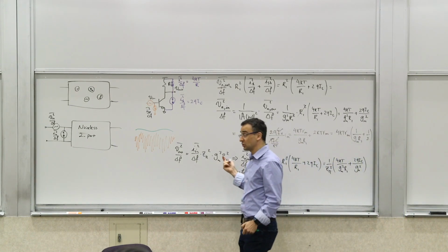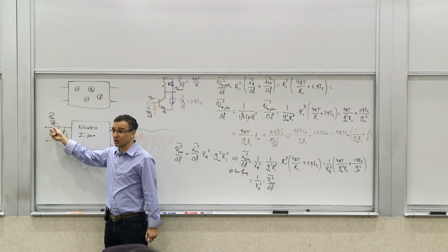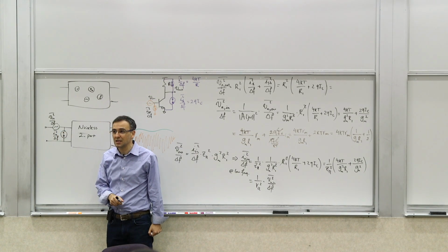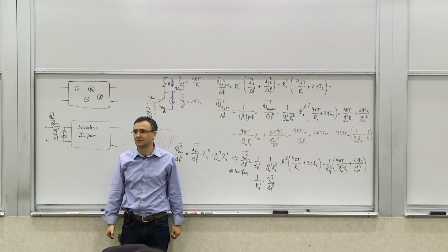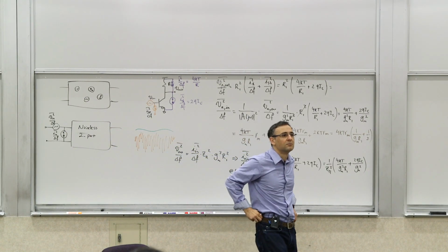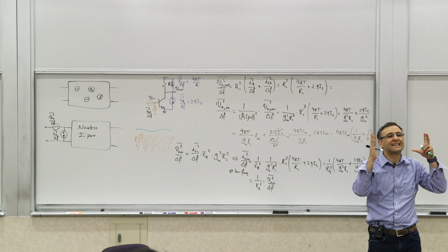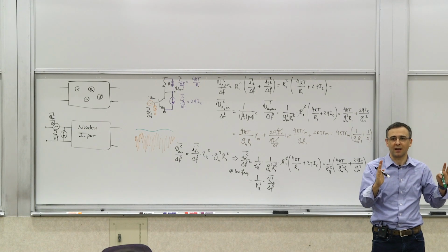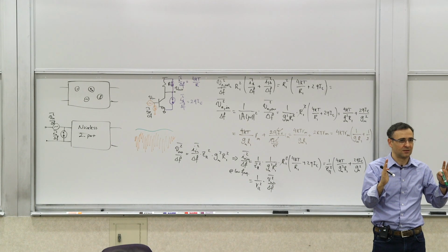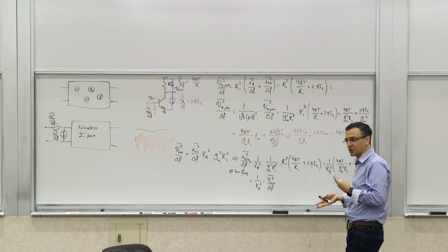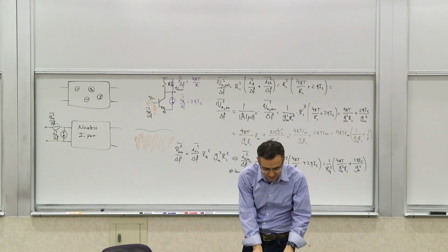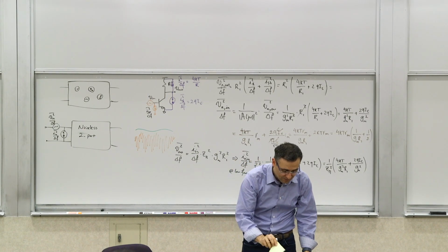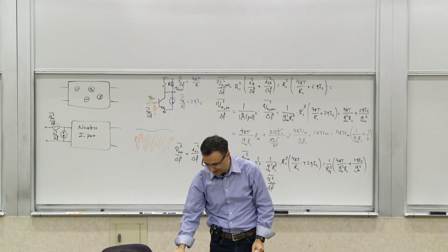So in general, what you need to know is the power spectral density of this versus frequency, the power spectral density of this versus frequency, and their correlation factor versus frequency. And if you know that, you've basically completely characterized that two-port network from the noise perspective. There are ways to measure these things, different methods of measurement. Actually, measurement of noise is a tricky proposition.